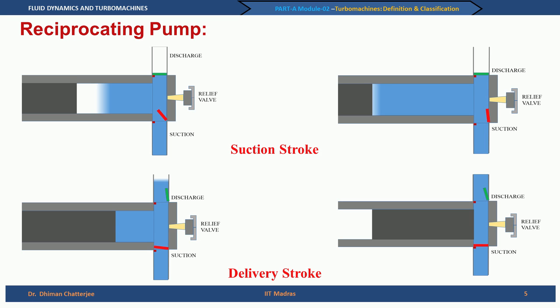So, in one cycle the pump will perform one suction stroke and one delivery stroke. So, you can understand, there is a suction stroke in which the fluid is admitted into the cylinder, and there is a distinct delivery stroke in which the fluid is released or discharged to the downstream side, that means the flow can never be continuous.